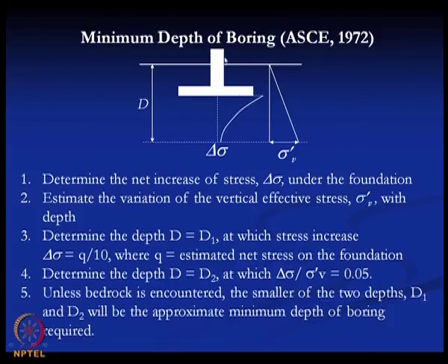If we apply load at the foundation, what would be the net increment of stress at different depths? We can calculate that, and various equations are available. Later on, when we calculate the settlement, we will show how to calculate this increment of stress due to the applied load at different levels.